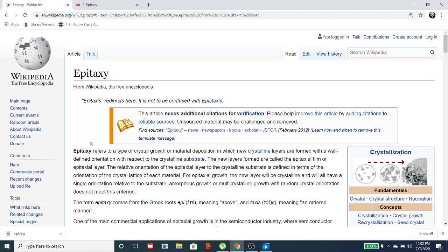Then we talked about the Czochralski process, through which we can grow the crystal throughout. We can grow the ingot, the substrate, and we got a cylindrical ingot, in the picture I showed you in the previous lecture. And afterwards, after slicing into wafers, we polish it and try to make it less contaminated. So that's our goal.